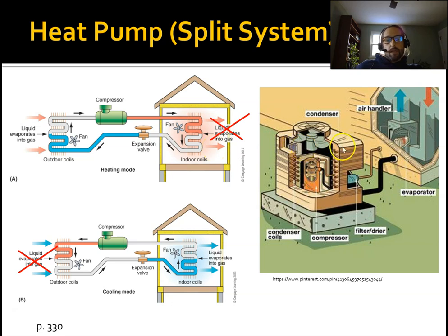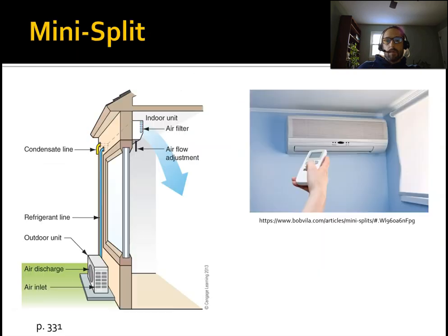Okay. Then when it's in heating mode, everything just reverses. There's a reversing valve in here that kicks in, reverses the flow, and then this becomes your condenser coil. So they get actually warm. The coils get warm. You blow that air, that return air across, goes through the filter, and goes across the warm coils. And so that's the benefit of a heat pump system, is that you can heat and cool with the same components. You just have to add a few valves and that reversing valve.